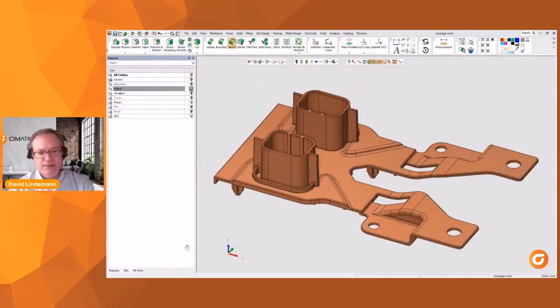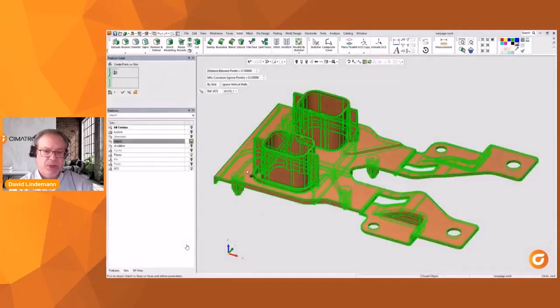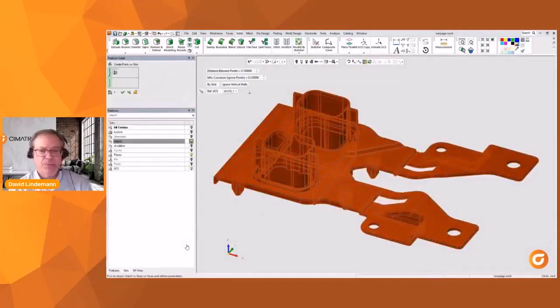Okay, so to begin the method of compensating, I'll first of all create my own point cloud. So I'm going to spray the points across the CAD file, and where those points touch, that's going to be my reference. I can control the tolerance, of course, the amount of points I want to use, by how far the distance apart will be. Do I want those to go up the vertical wall? Yes, I do, because I want to capture whatever draft angle is there. So that will become a huge factor.